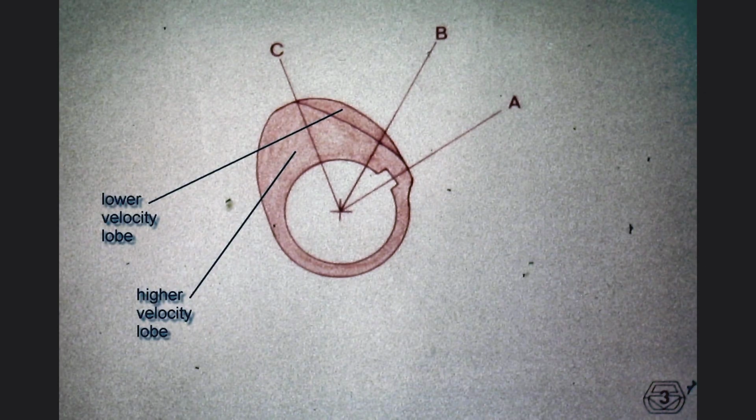Since the RPM of the print shaft is always the same when it is turning, this means that both cams move the cam follower through the same distance, but the cam on the right, in the foreground, does it in less time. The angle for the cam in the background is defined by A, center C, and the angle which starts to operate the cam follower much earlier is defined by B, center C.